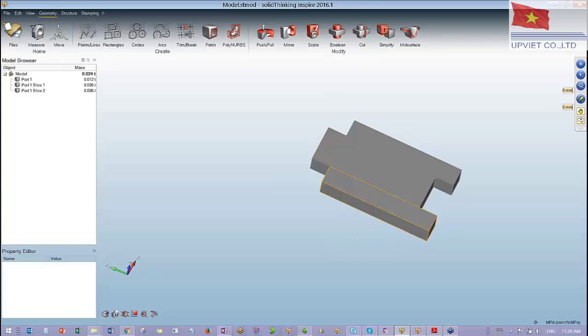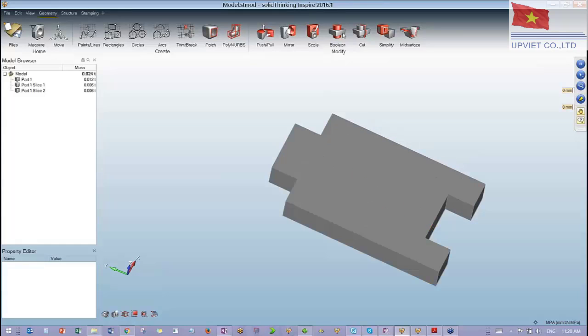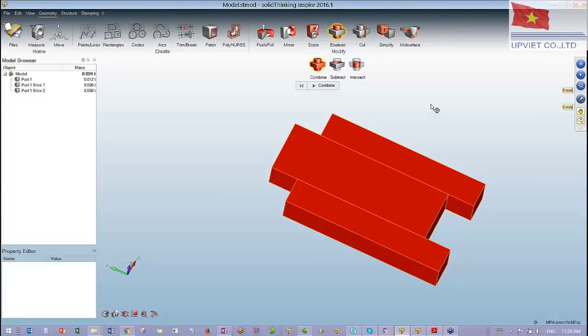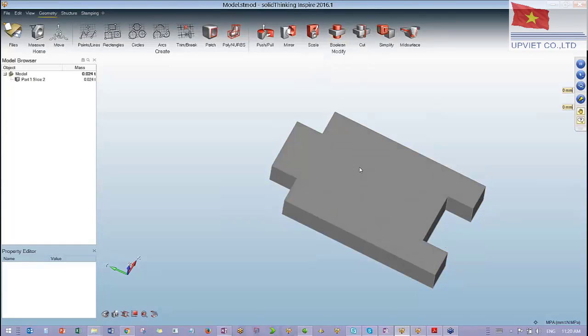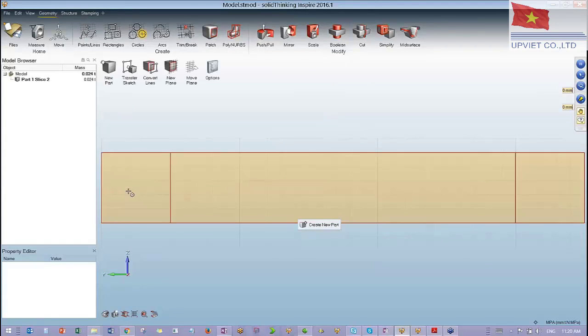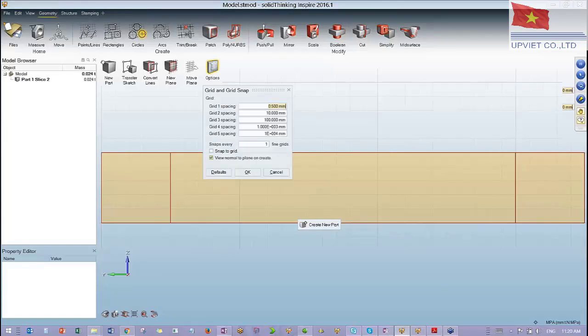My design space creation is almost ready. Let me do one boolean so that I can combine all those parts together. And I'm done. The only thing remaining is to create some holes and cutouts, which again you can create very quickly in Inspire.